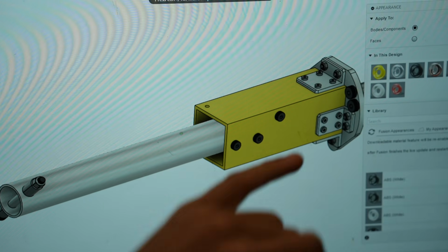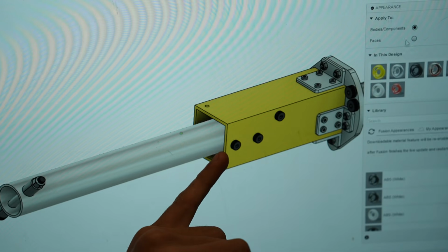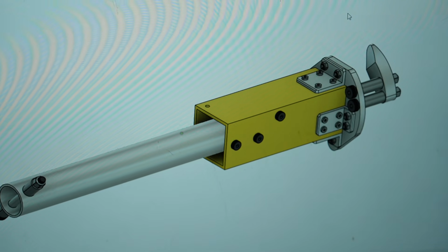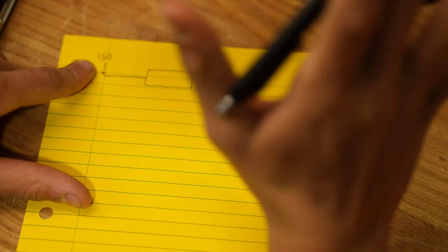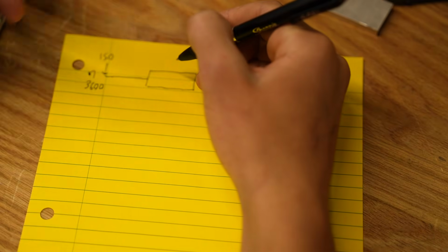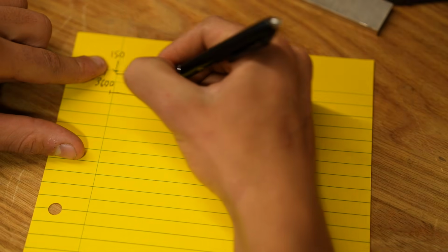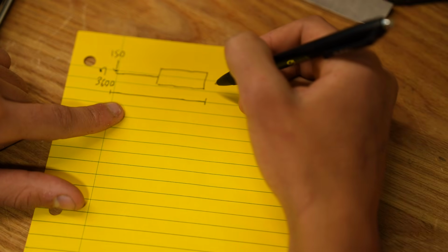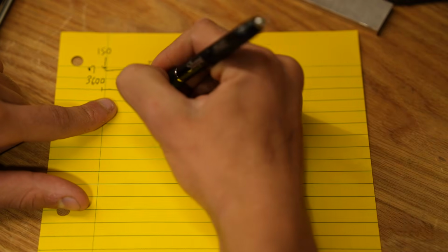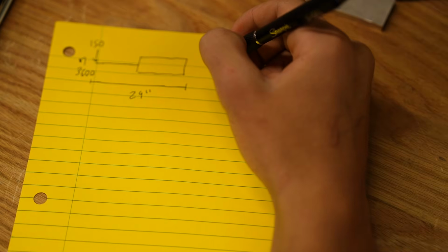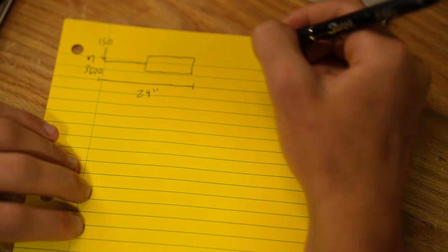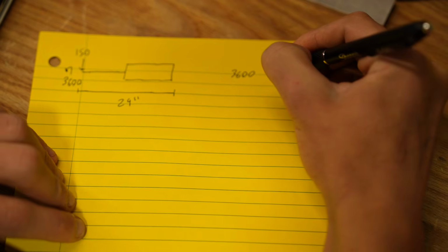We're now going to move to talk about our outer box. So the outer box, much like the inner tube, undergoes this much force, in a very similar loading to the tube. So we're going to have the 3600 of torque and the 150 pounds of load at a distance of 24 inches. So we're going to calculate the bending moment again, which is going to be 24 times 150. And we get 3,600. So we get 3,600 in both directions.